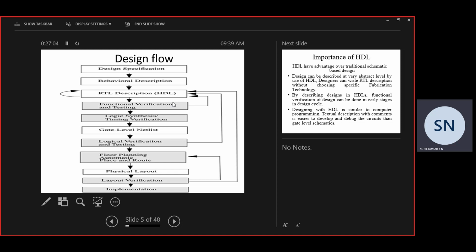Supply 1, supply 0. These are the limits of the power supplies. This is supply 1, this is supply 0. These are nothing but keywords which are available in the Verilog library. So when I use supply 1, I am giving it as power. The power signal is nothing but VDD. Supply 0 is nothing but ground.